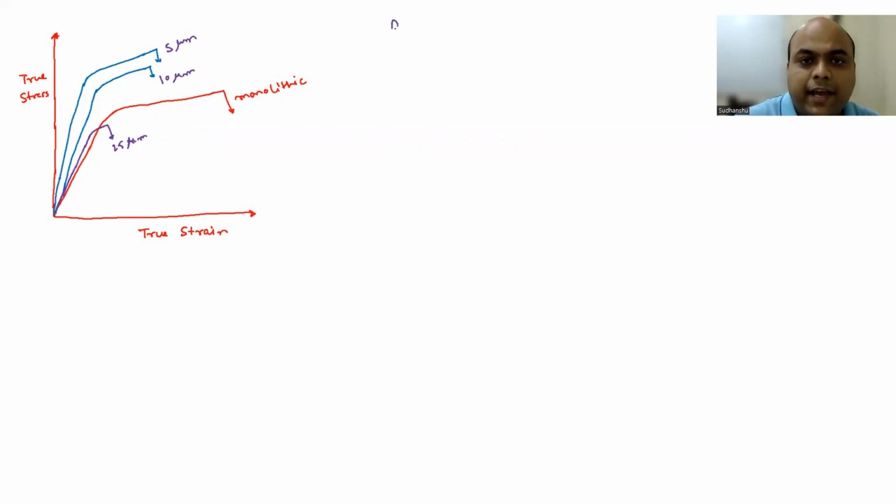Okay. So let's say we have aluminum silicon carbide, again MMCs, and we have extruded it. Okay, and this is for extrusion. So it depends upon the processing conditions also. Okay, this one is for the extruded one. So what are the observations you are seeing here? That if you decrease the particle size, you are going to increase the modulus as well as yield point. See, the slope of the 5 micron curve is higher than the 10 micron curve. Similarly, the yield point is higher for 5 micron than 10 micron. That is point number one.